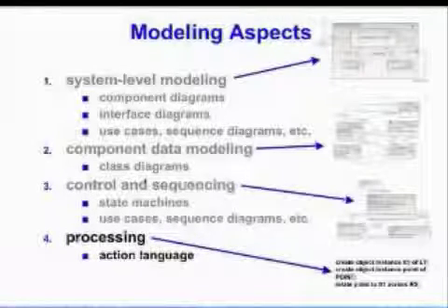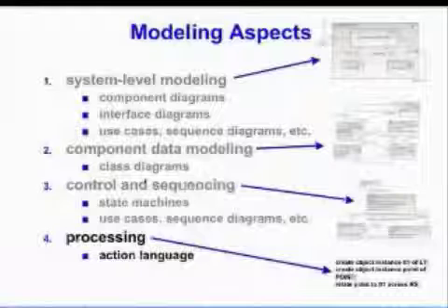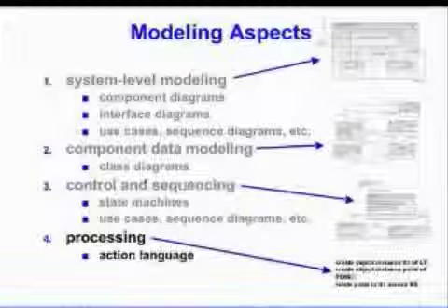Inside each state, we have captured the behavior of the processing that occurs in that state. In BridgePoint, we use an action language. And if I look at the collecting state, I can see that while the route is in the collecting state, I'm going to create an instance of a timestamp and create the point and relate it to the route, and then generate an event causing me to move to the next state.